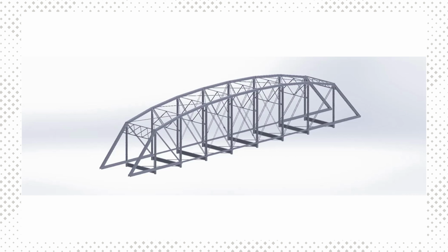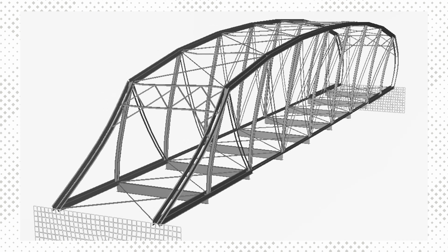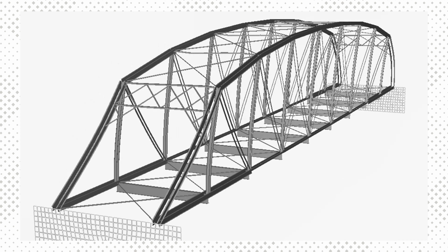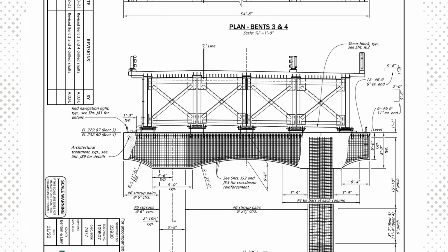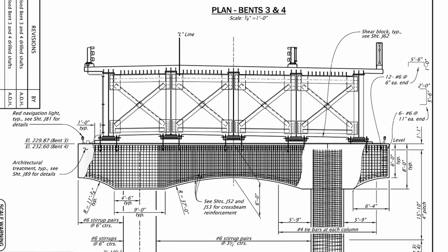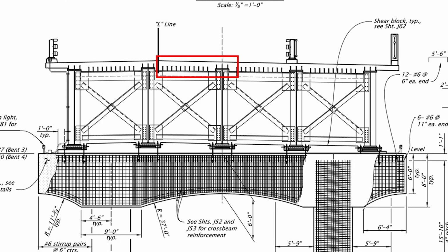Trusses are three-dimensional systems, though we often think of them as two-dimensional. In the Van Buren Bridge, the vertical trusses do the heavy lifting. However, if they weren't laced together with horizontal bracing, they would simply tip over. With horizontal bracing, the truss remains stable for vertical loads and can withstand lateral forces. In the new bridge, the girders are stabilized by cross frames and concrete deck, which is attached by headed shear studs. These keep the beams from rolling over and transmit lateral wind and seismic forces into the substructure.